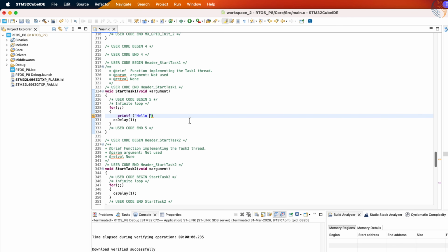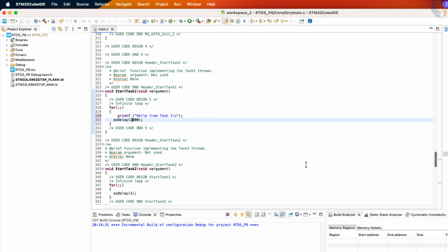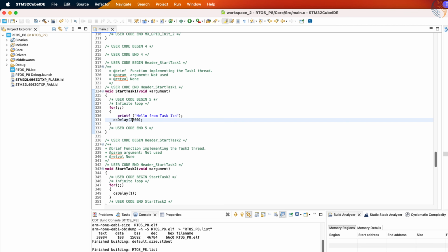That's why it is essential for you to monitor the stack usage according to your specific microcontroller and the unique requirements of your project. Based on those measurements, you can make informed decisions about how much stack space each task needs, and how much code you can safely write inside it without causing problems.